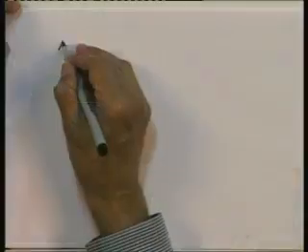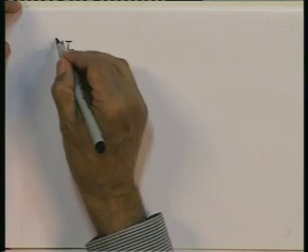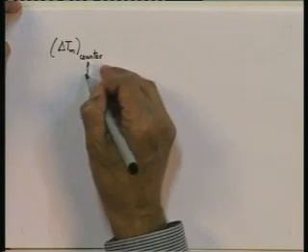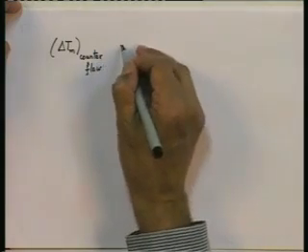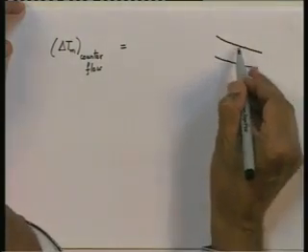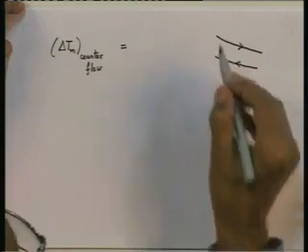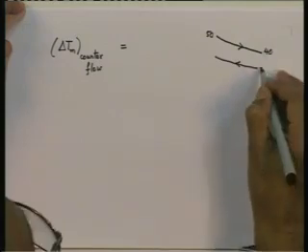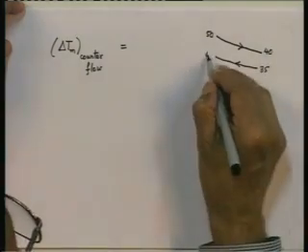What is delta T m in counterflow? Let us get the value of delta Tm in counterflow. Delta Tm will be equal to, let us draw a sketch as if it is a counterflow situation, starting with 50, going out at 40 on the hot side, cold side entering at 35 and leaving at 40.